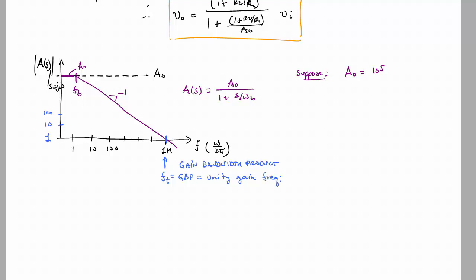Okay, so let's suppose that the gain bandwidth product is equal to 10 to the 6 hertz, okay, megahertz. What would be the corner frequency FB? Well, if we know that the gain rolls off at 1 decade in gain per decade in frequency, then we can work our way back from our unity gain at 1 megahertz back up here, right?